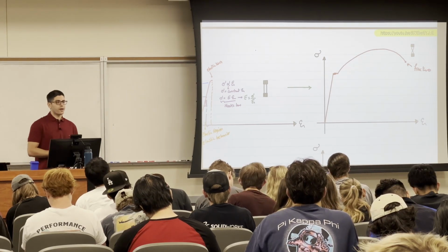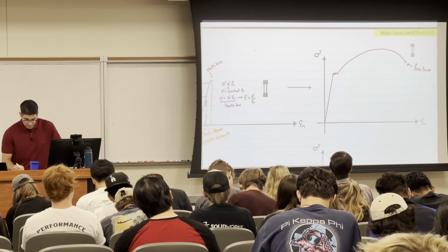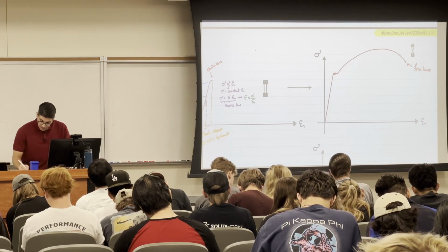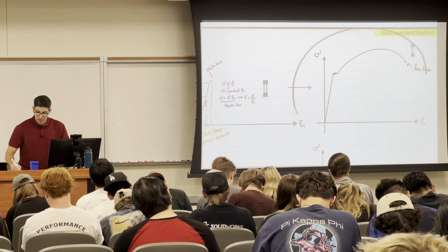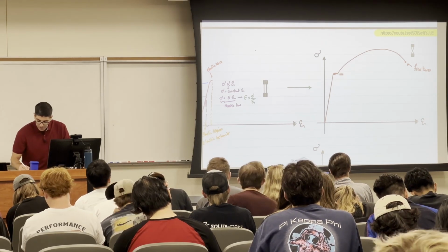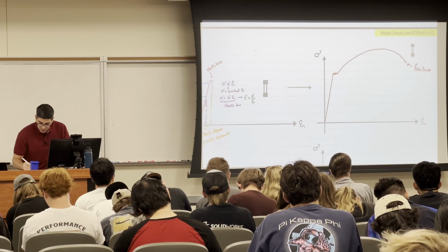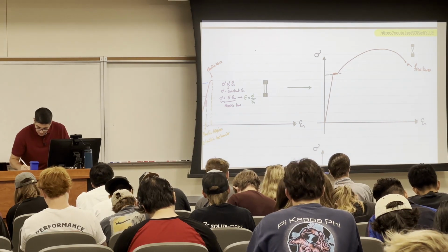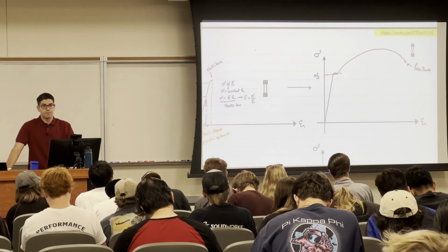Okay, let's talk about this. If you have a curve like this and I want to find the yield strength, it is at the point where you have these ups and downs. So this is your yield stress, okay?